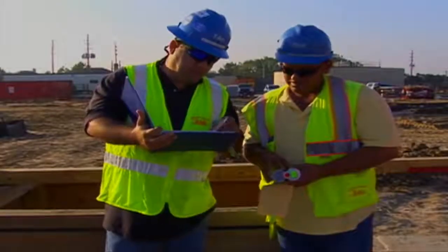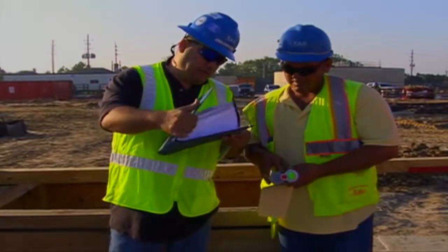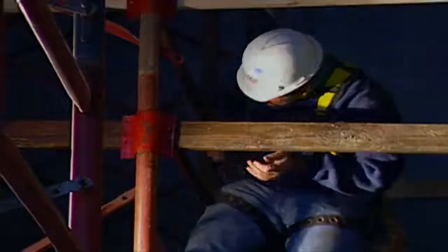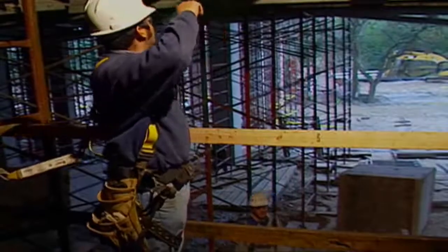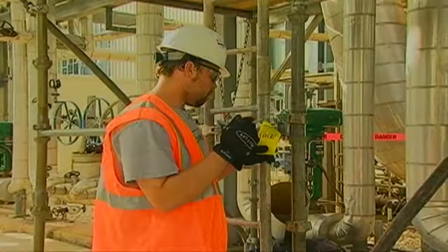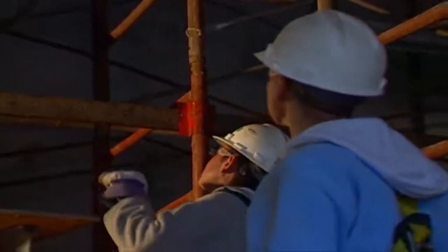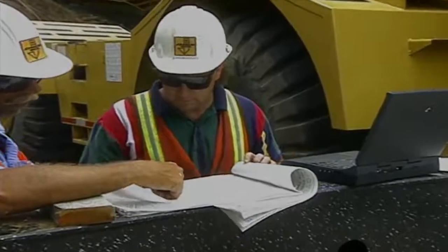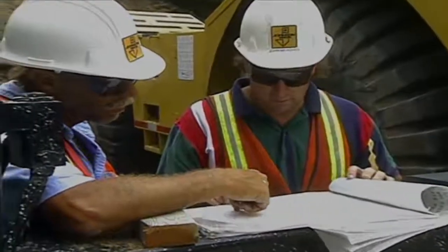A competent person has specific duties when it comes to scaffolds on a job site and is required to be present on all sites where scaffolding is used. They are to train employees involved in erecting, disassembling, moving, operating, repairing, maintaining, or inspecting scaffolds to recognize associated work hazards. The competent person must choose and direct the workers who erect, dismantle, move, or alter scaffolds.